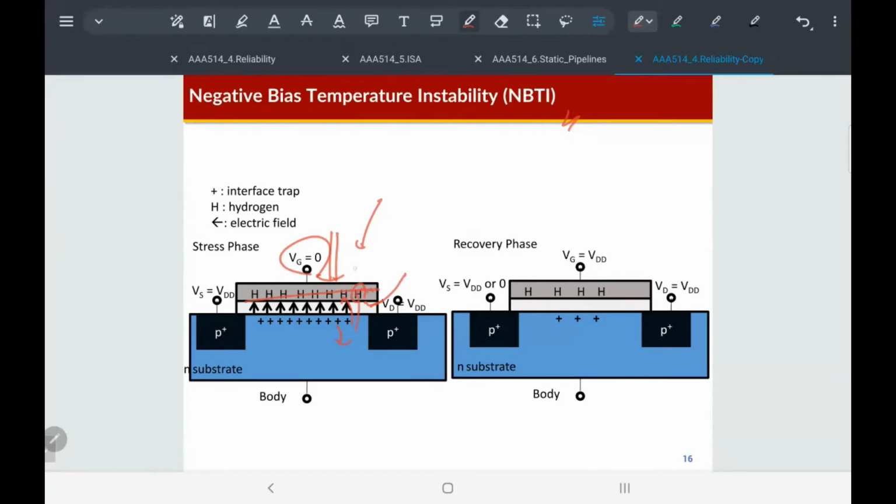The gate is connected to the metal layer, but because this voltage was negative, some holes can move to this metal gate, and then the holes can be captured in this metal.